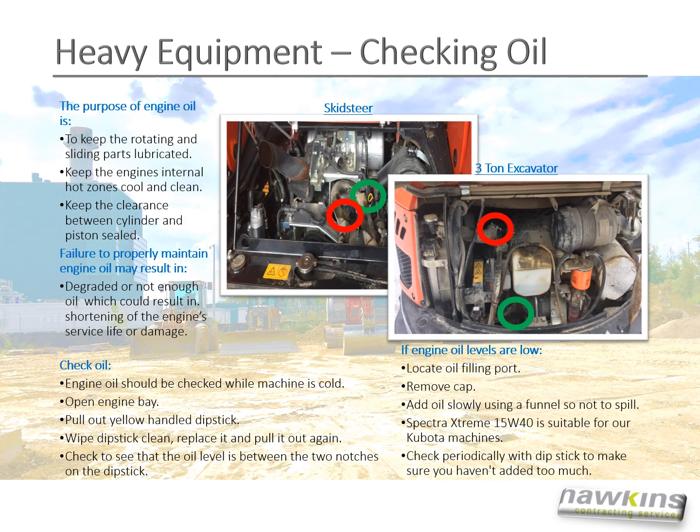Checking oil. Engine oil should be checked while the machine is cold. Open the engine bay, pull out the yellow handled dipstick, wipe the dipstick clean, replace it, and pull it out again. Check to see if the oil level is between the two notches on the dipstick.